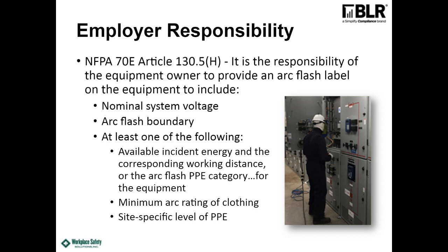So even if they use the tables, they have to know what the clearing time and the fault current is. And the clearing time is not just based on time current curves, but it's also based on maintenance of the equipment as well. So it's the responsibility of the employer to provide that information to the contractors and the employees. So that's where the engineering study comes into play. If you do an engineering study and you've got labels on it, you just tell the contractor, go by the labels. Bang, you're done. You've done what you need to do to tell them what the hazard is.